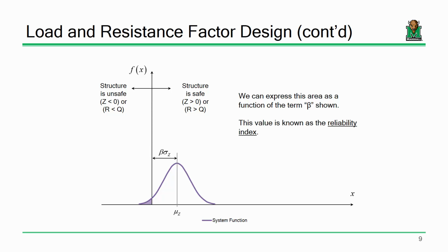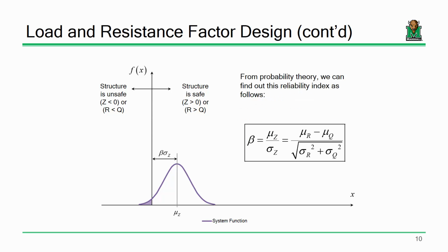So that's why we're a little more stringent on connections. If you remember, if you took steel design and you look at, let's say, tension members, the resistance value, that phi value, is 0.9 for yielding, but 0.75 for fracture, because you're looking at that connection region. It's more stringent there. That's why we use that lower resistance factor. So just bringing it back. All right.